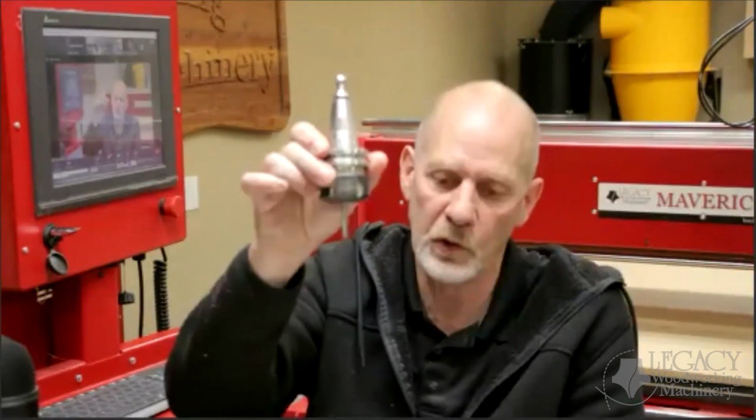But with the little light touch pads, does that even matter anymore? Or not nearly as much. I never really like to do my Smart Tool setups with a V bit or something that comes to a really fine point. So I will typically use either an end mill. You can see this one's only 1/4 inch. That'll work just fine.